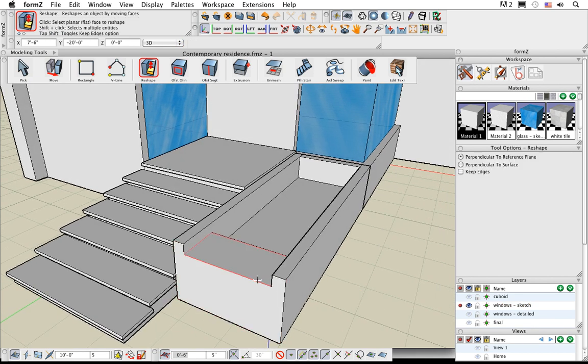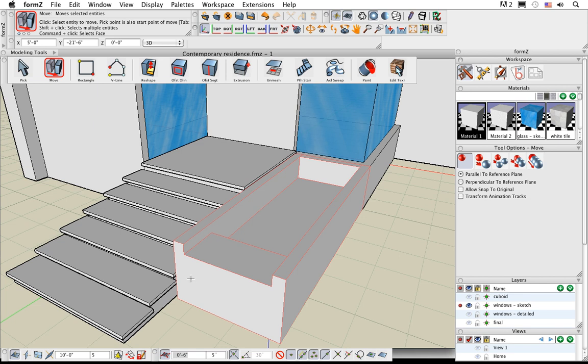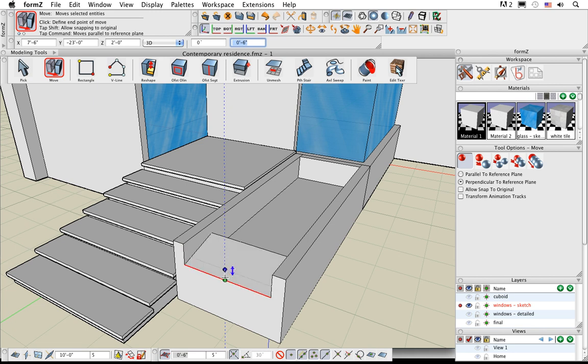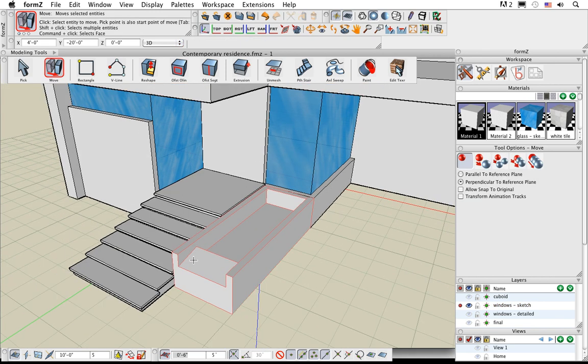I'll tell you what, let's give a little slope to that. So let's use the Move tool. I can select topological parts by holding down the Command key on Mac or Control key on Windows, and now you can see that I can grab just a point, segment, or face and move it. So that's different than reshaping. Reshaping is Booleans. Moving is you're just moving the object, the segment or the face. Big difference between those two. There's this little slope for the waterfall. All right, let's add a couple textures on here.